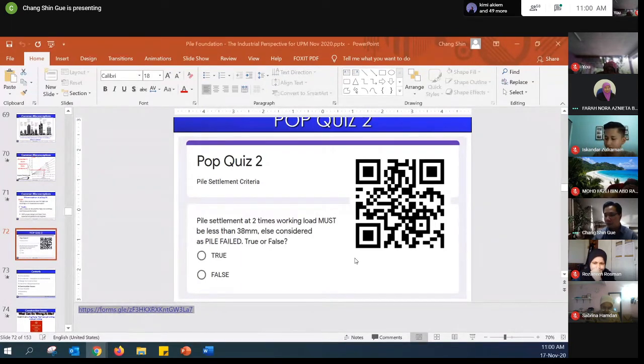Okay. So boring is not necessarily with casing. Some boring you don't need casing, is it? Some boring you don't need casing. If the soil is actually very good, then you probably don't need it, but usually you will need it. Okay. And also when you drill, there's a bentonite fluid that helps you to hold the borehole without the casing. That helps as well. Okay.